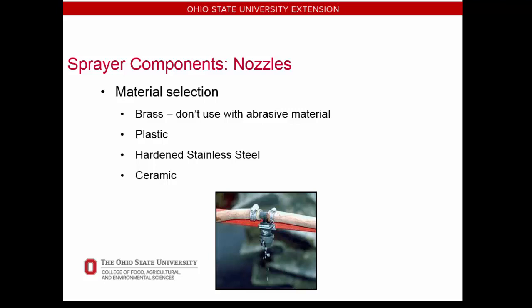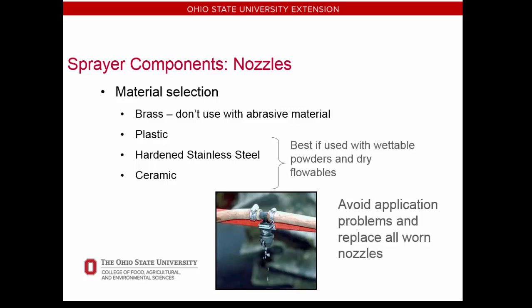Plastic or nylon nozzles wear rapidly with emulsifiable concentrates. The best all-around nozzles that last fairly long are hardened stainless steel. However, if you can get over the sticker shock of ceramics, they may be the best nozzles since they last for quite a long time.